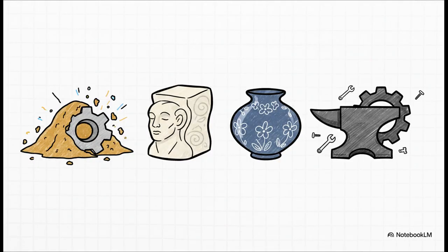Now, you might think these extreme temperature containers are all made out of high-tech composites or super specialized alloys, but look at this list of common mold materials: sand, plaster, ceramic, and yes, sometimes other metals. Sand? Really? Yes, sand is incredibly common because when you mix it with the right binders, it holds its shape, it withstands immense heat, and, best of all, you can just easily break it away once the part is finished. It's a beautifully simple material solving a highly complex industrial problem.